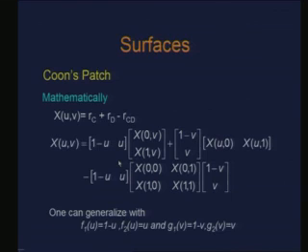So, now in fact, if you observe, these are the sort of blending functions which are being used here, 1 minus u and u, 1 minus v and v, right. So, one can even think of having some generalized form of this Coons patch, where I can define 1 minus u as some function f 1 u, right, and u as some f 2 u.